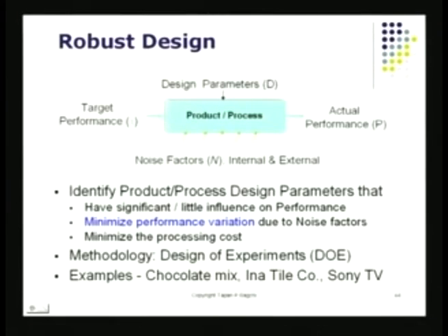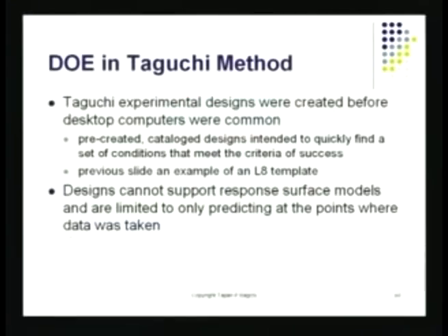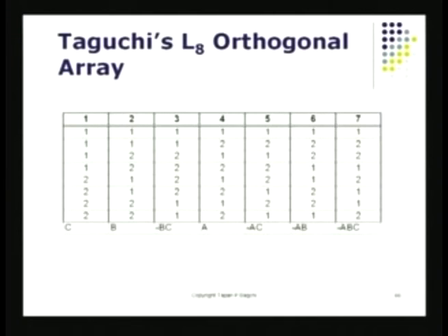Of course, when you're manipulating simultaneously many different variables, the only way to do that is using a DOE setup. And we can, of course, see DOE is a key element in the Taguchi method. And if you look at the plans which are used, Taguchi's plans, they look a lot like the full factorial design. But something I've got to remind you of, Taguchi is not trying to use ANOVA. Taguchi does not really try to explicitly monitor or measure interaction between factor effects. Taguchi does not try to do that. He does try to figure out the interaction between noise factors and design factors. That is one thing that he tries to do.